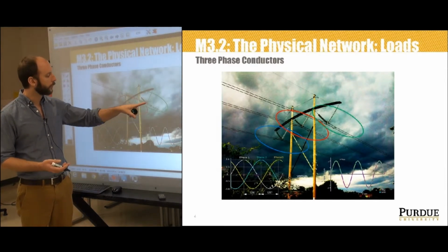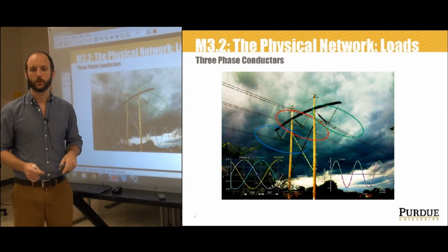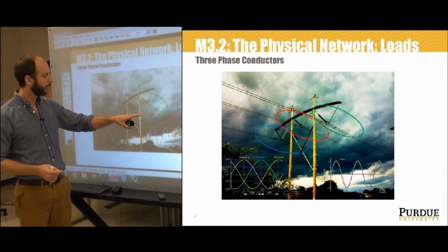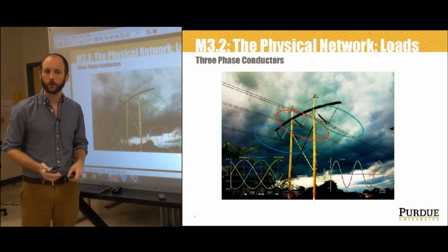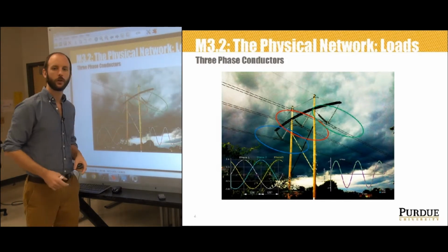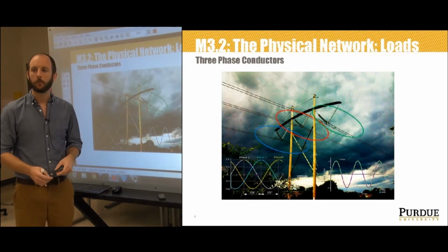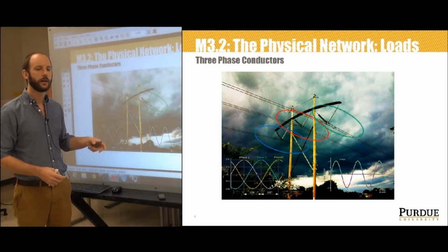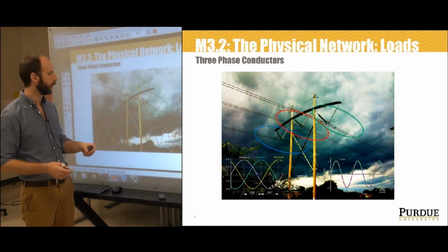Now, despite the fact that these are at the same magnitude of voltage, there is a phase difference, so there is a voltage difference between those. So if I were to do a Kirchhoff's voltage law between these 2 points, 0 volts. If I were to do a Kirchhoff's voltage law between these 2 points, it's a non-zero voltage, so there is a voltage difference between those wires. So you'll always see bundled wires in multiples of 3, right? 2, 4, 6, 3, 6, 9, etc. I said that there were only 6 wires in this.